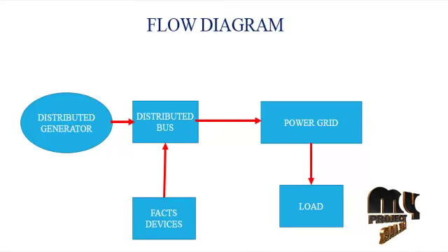The system impedance Xs corresponds to the short circuit MVA at the SVC bus, and is obtained as Xs = Vb squared over S. The basic concept of voltage regulation is the addition of an appropriate in-phase component to the prevailing terminal bus voltage in order to change its magnitude to the specified value. Thus, voltage regulation could theoretically be achieved by a synchronous in-phase voltage source with controllable amplitude plus or minus delta V in series with the AC system and the regulated terminal.